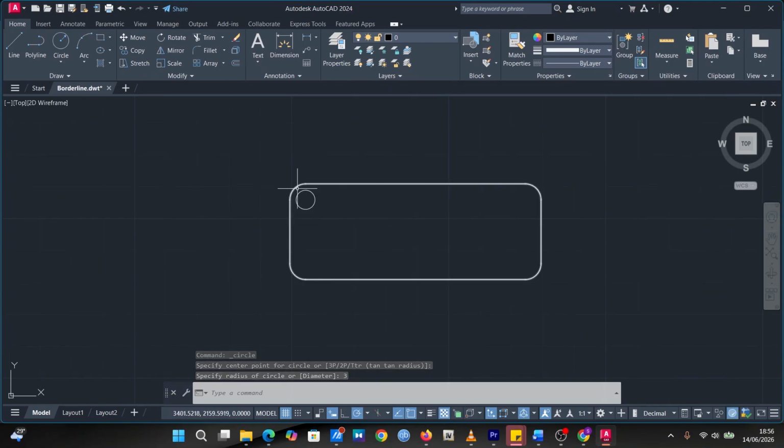Now we have it at the left corner here. We want to duplicate this circle in all corners of the rectangle to make it 4, and we make sure we have an appropriate measurement for each of them. We know the distance from the middle of this circle to here to be 70, because if you remember, we used a radius of 5 to cut here, and a radius of 5 to cut here, and the full length was 80. So 80 minus 10 is going to give us 70. That means the center from here to here is going to be 70.